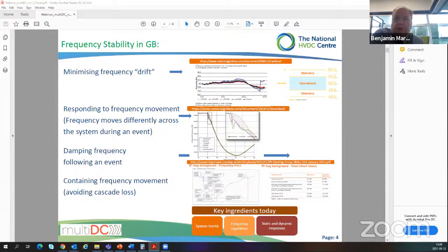There's also a question of responding to a loss that happens and could be incurred in the system. We contain those losses to a maximum of 1800 megawatts, but where they happen and how they then perform, from the inset in the middle there, the frequency can be different in different parts of the GB system. That's a key point for the GB network, that you can see as much as a 20% difference across the network between values. And you can also see significance of the absolute frequency. So that needs to be borne in mind, because we're moving towards faster and faster.